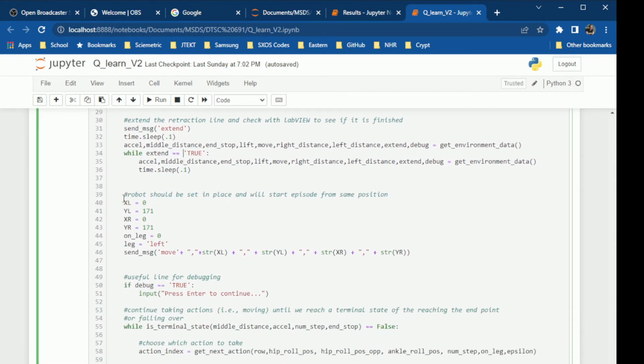And this here just defines a starting position for the robot to be, so it's its starting stance. X's of 0 mean the feet are directly underneath the robot, and then 171 means the knees are crouched, or it's starting from a crouching position. And just so you understand what these numbers mean, without going into too much detail, I measured the length of the robot, and then I defined the conversions to be from PWM to millimeters of the robot. So if I were to put in 0 and then the total length of the leg, which is 179 millimeters, that would be standing straight up.